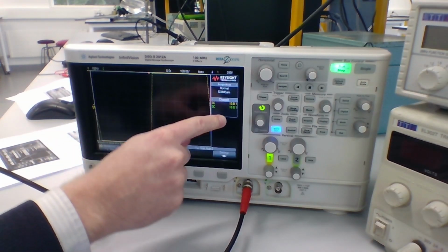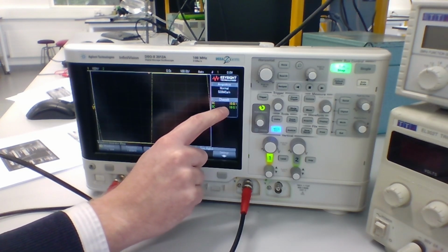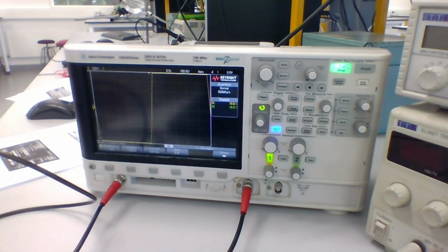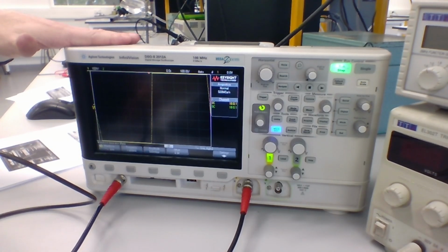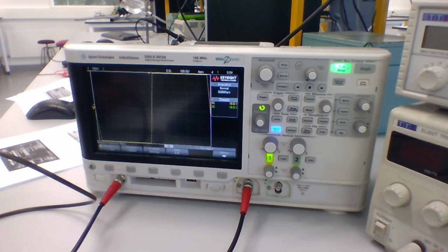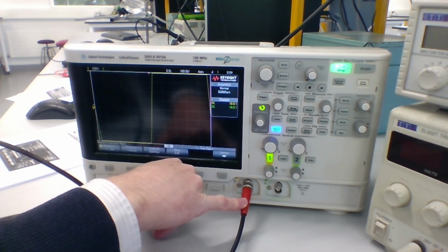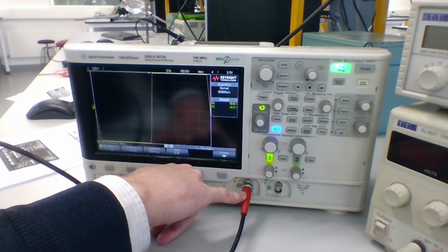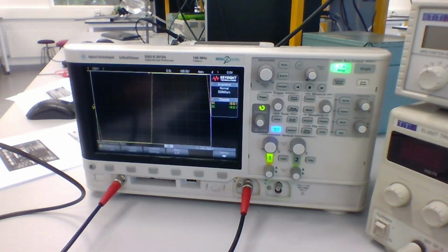If we look on the oscilloscope screen here, we can see when it says channels, it says DC for both channels in yellow and green, and they're both set at 10:1. In other words, this assumes that our oscilloscope probe is set to a 10 times attenuation. So it's saying, okay, what's coming is 10 times smaller, so I'm going to increase it by a factor of 10 to correct for that change. However, when we're using a direct connection like this BNC to BNC cable, there is no attenuation. This is a 1-to-1 connection. If this is set to 10-to-1 and this is set to 1-to-1, what we're measuring on the screen is 10 times larger than it is in reality. So we need to change that.